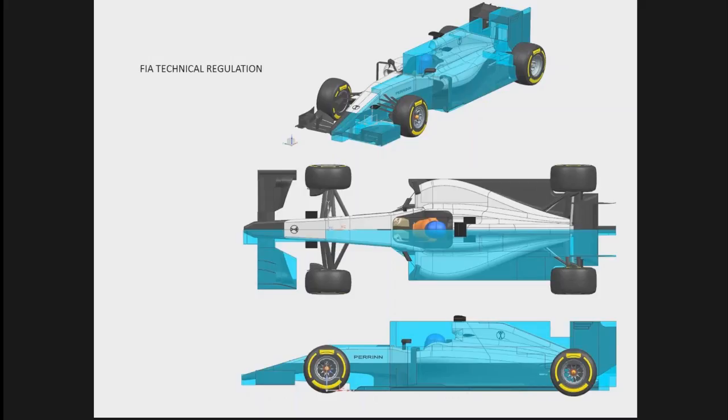And we've done this as well in the past. The simulations take longer, but they can give you slightly more realistic results because it's like having a flow effectively moving through time along the car, so you can see the transient effect. So behind the tires, for example, you can see turbulence moving left to right and things like that.